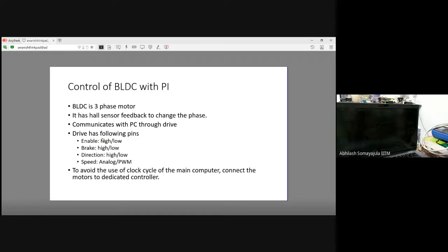I have I2C, I have SPI, all those communication protocols are there. I can straight away communicate between those. So these are GPIO pins on the Raspberry Pi. Yes, you can actually give out these different protocols like I2C. Certain pins can communicate on I2C, certain pins can communicate on SPI, or some other protocols.